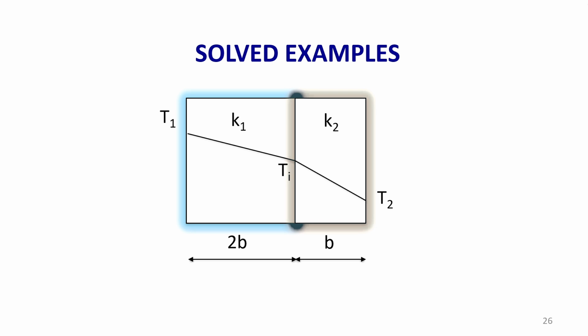So, here of course, they have considered only conduction, because if HA and HB, TA, TB are not given, then the convection heat transfer can be neglected for that particular numerical question or example. So, we can solve by calculating only the conduction resistance of that particular configuration.